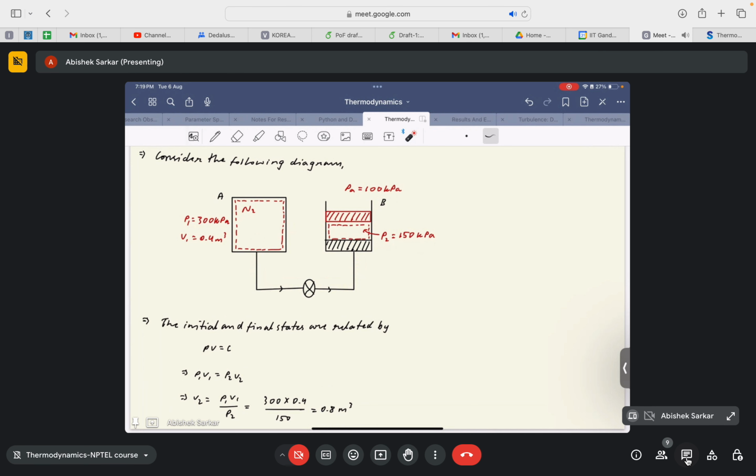So the system in this case, see, this is important, is both this chamber and this area, okay. Is it clear? In this case we are just ignoring the volume of gas within the pipes, okay. It was discussed by Professor Anand that he is ignoring the volume of gas within the pipe and the valve, considering that the diameter of the pipes is much smaller than the size of the chambers, okay.